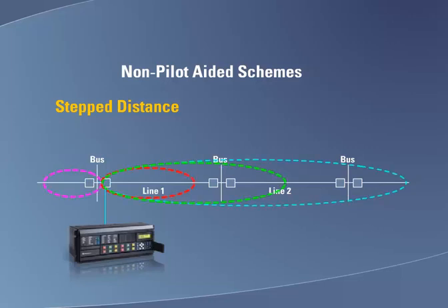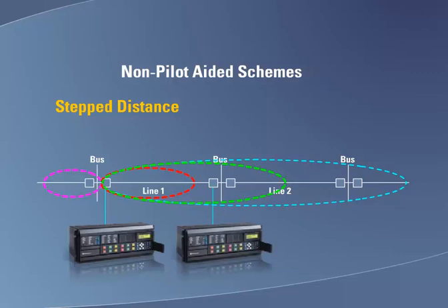However, the breaker on both ends of the transmission line must be opened to completely clear a fault. Therefore, another distance relay must be located on the right end of the transmission line to control that breaker. The relay on the right needs to be programmed with the same characteristics as the relay on the left. However, this one will be set up to be protecting in the opposite direction. Now, the zones of protection of each relay will detect any faults that occur on our protected transmission line. These relays will then proceed to open the breaker and clear the fault from their own respective end of the line. Each relay will also have ground step distance zones of protection, which are identical to that of the phase step distance zones. The difference being that the ground distance elements are used to detect single phase to ground faults.